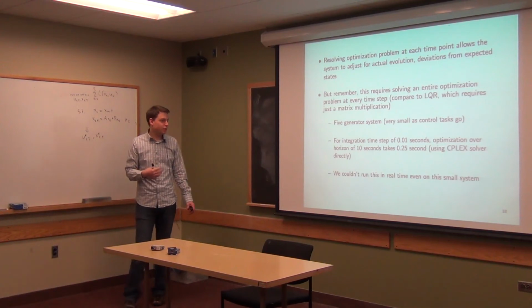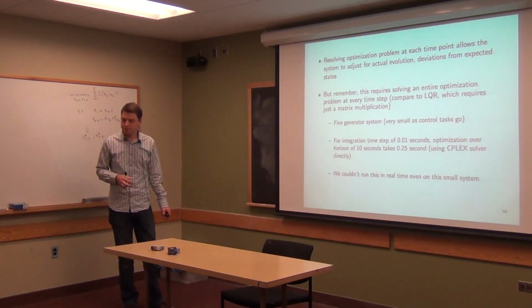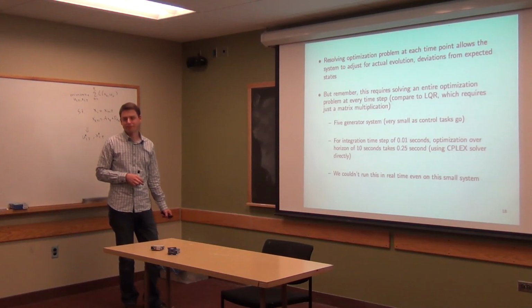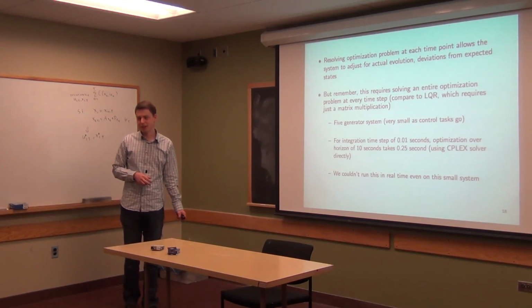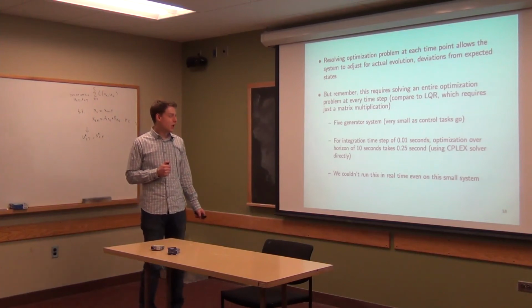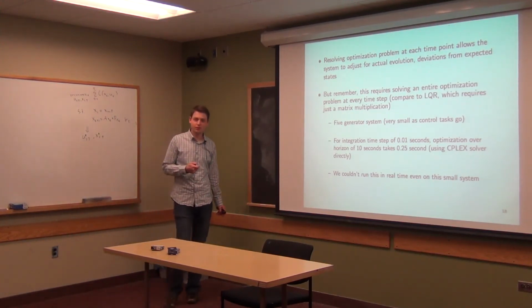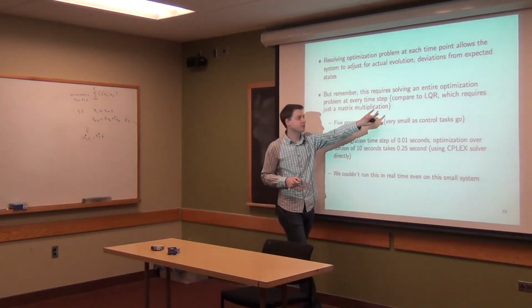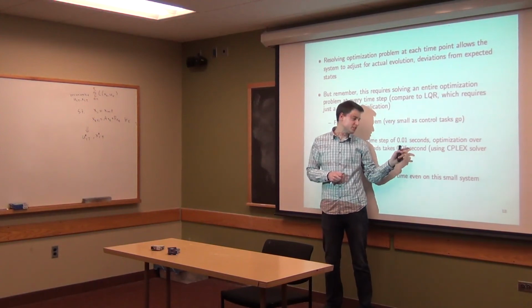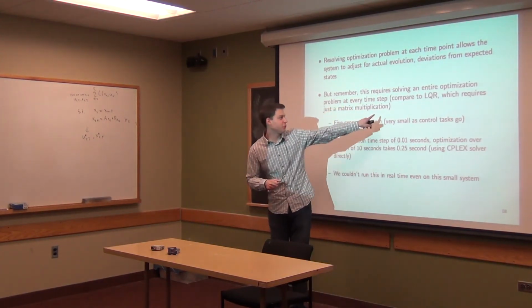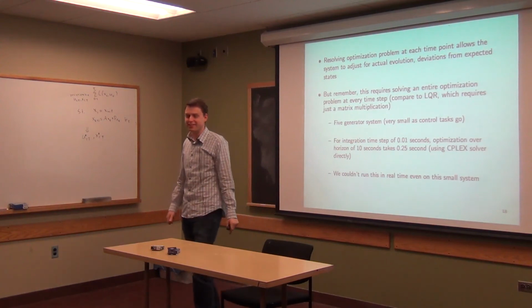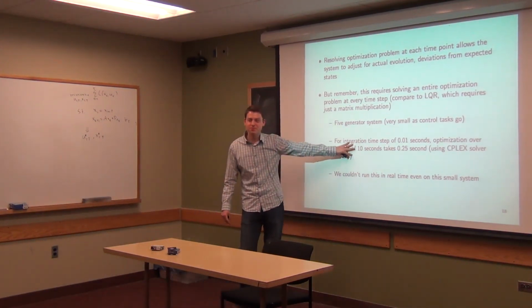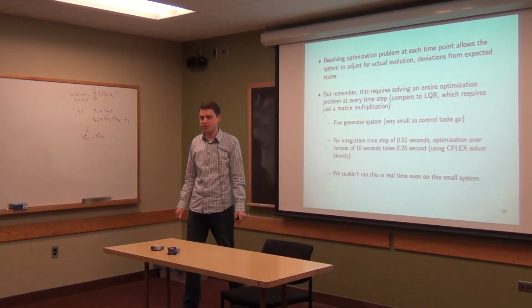Because the downside of MPC is that we do have this large computational cost associated with it. And compare this then to LQR, where the cost is a matrix multiplication. A 5 by 10 matrix you're multiplying by a 10-dimensional vector. And you can imagine which one is easier to do, right? The cost is incomparable. This takes microseconds, if that, whereas this takes a quarter of a second. I think actually microseconds would be way too much for this. We're talking about maybe hundreds of nanoseconds, maybe not even, less than that. Anyway, very, very fast and very, very slow, by several orders of magnitude.